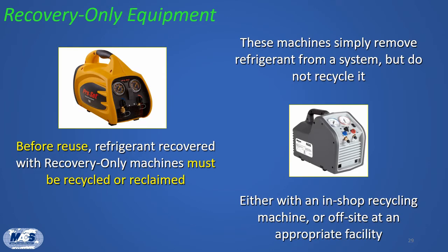But there's a lot of situations where it's just not practical to use a full-size charge cart to service an air conditioner. For example, if you provide on-the-road service for your customers, it's much easier to carry around recovery-only equipment so that you can recover the refrigerant out of the system before you perform any work.